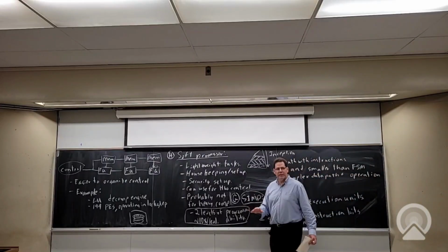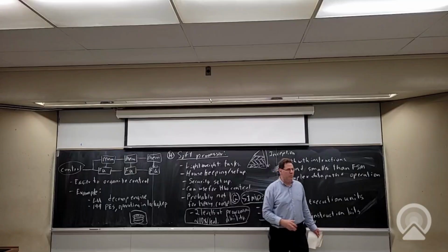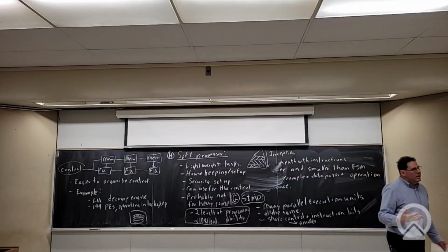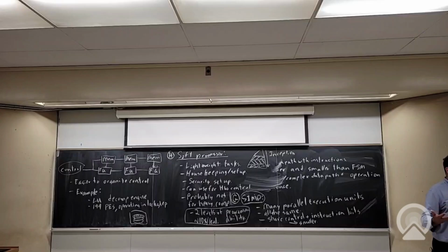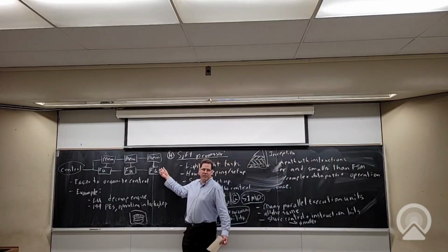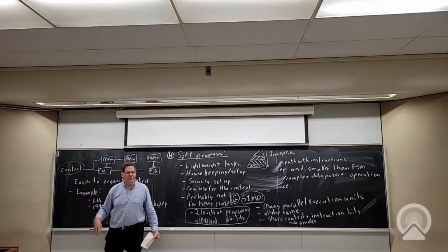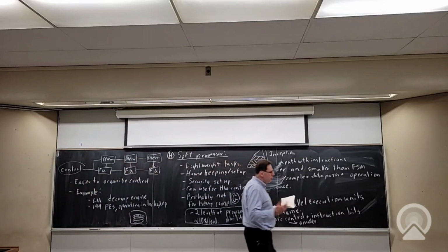So usually, if you're going to start getting into higher end, superscalar, out of order, go for a hard processor. Those are starting to become large enough that they're no longer lightweight and they probably don't make that much sense. You can also add SIMD units to them. But again, if you're going to do a lot of that, you can use it to control a bunch of custom SIMD units like this. So that's fine, because your processor is a relatively small part of your data path. Does that make sense? That is one of the advantages of a soft processor.